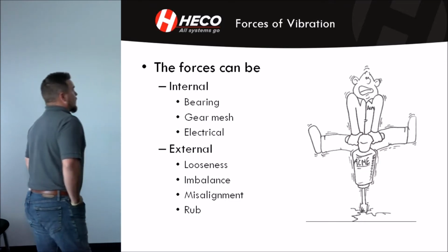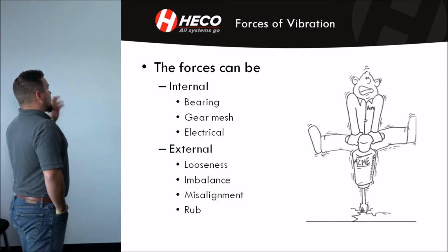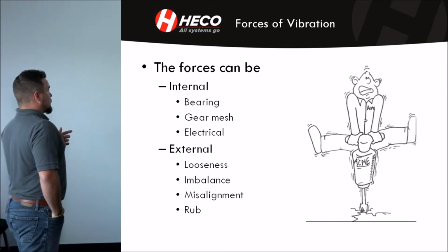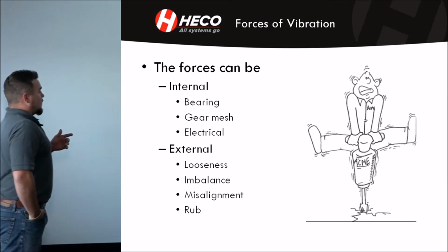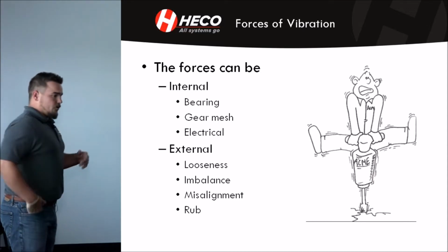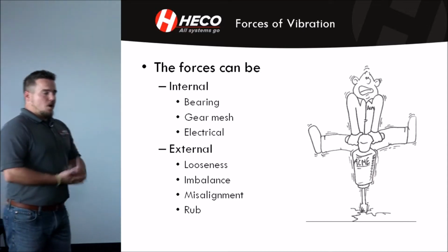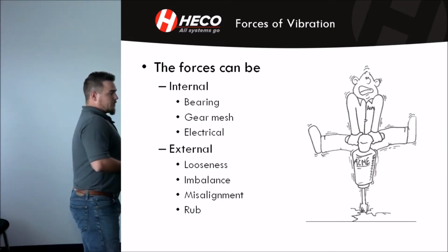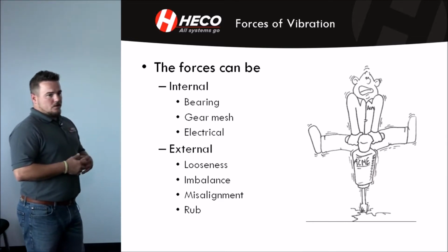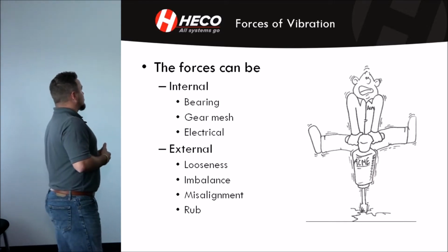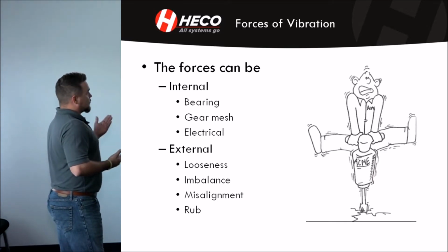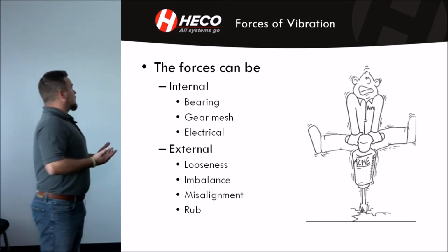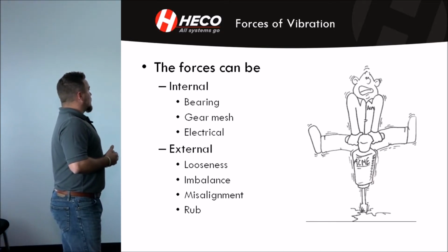All right, the forces of vibration. Forces can be internal or external. Things like bearing, gear mesh, electrical, these are all internal. Examples: bearings, you know, you have an outer race, an inner race, ball spin, fundamental train frequency. Gear mesh, same thing. You have two gears, they're internal. You got a broken tooth, anything like that, it's an internal force. Electrical, misalignment or soft foot, you might have an air gap variation that'll cause an electrical signal.